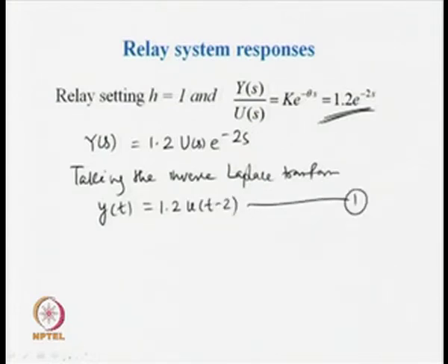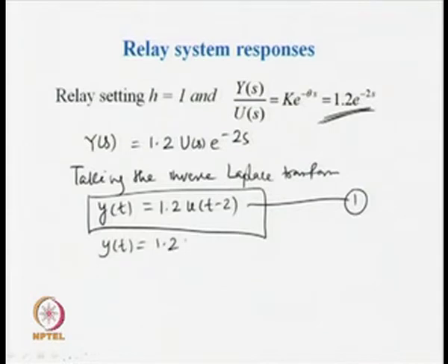So, what sort of equation have we got? A linear equation, but it is a delayed linear equation. This time delay gives us typical types of responses of a system. The system input is u and the output is y, but we have a delayed input to the system. Now, had there been no time delay, y(t) would become 1.2 u(t).